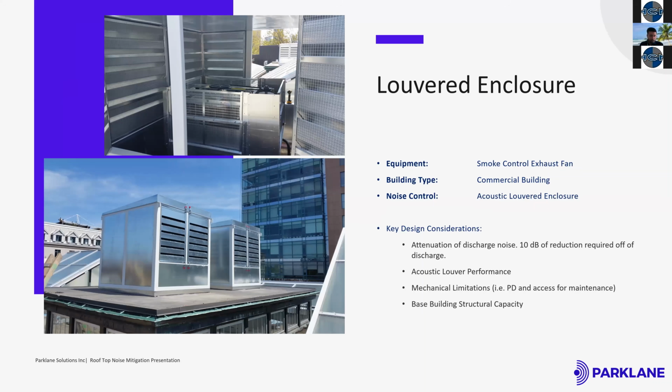Sometimes an enclosure can also be a louvered enclosure, where you have equipment that needs to be mitigated but still needs air to flow in and out. In that case, you can have a louvered facade, which is acoustically lined, and the enclosure itself is also acoustic. So whatever sound is coming from the pump or the compressor, it can absorb the noise, and essentially the transmission loss achieved by this enclosure will be whatever needs to be met, dictated by the acoustic consultant.